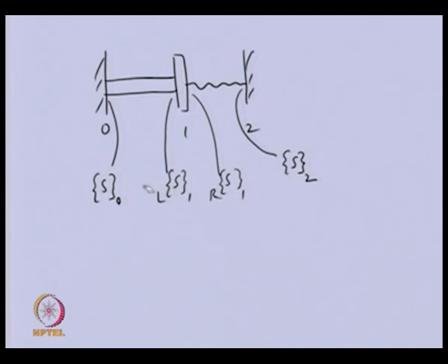Now, you can see that between these two state vectors there is a field matrix, and between these two we have a point matrix. This spring is identical to a field matrix because it acts just like a shaft with stiffness KT, now KT2, so it can be considered as a shaft directly.